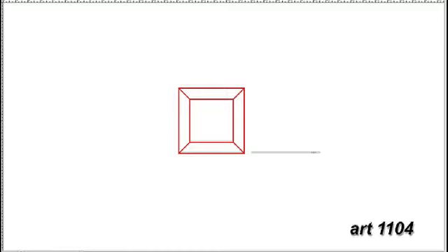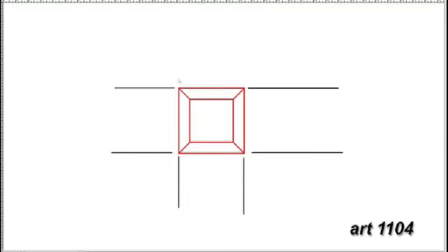And in a 1-point perspective, you can see that the majority of the edges that are in our scene are not receding into three-dimensional space, and in fact are parallel to our picture plane. And the rules of linear perspective dictate that the edges that are not receding into three-dimensional space will be depicted as parallel and will not converge.